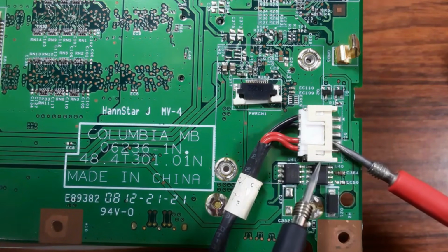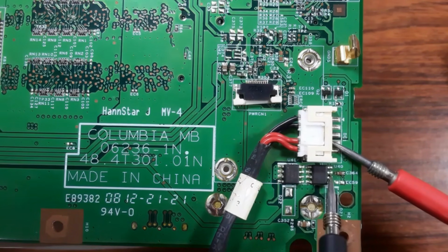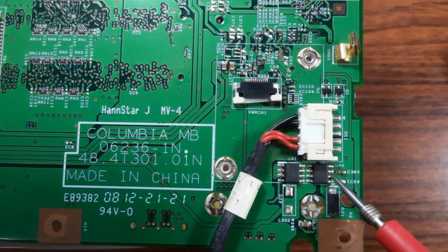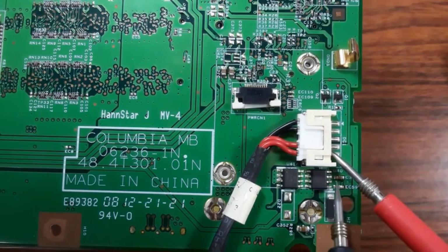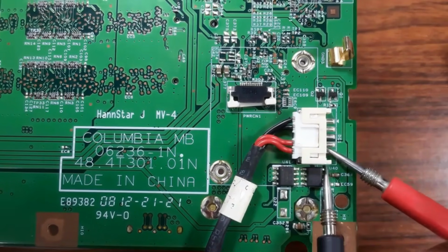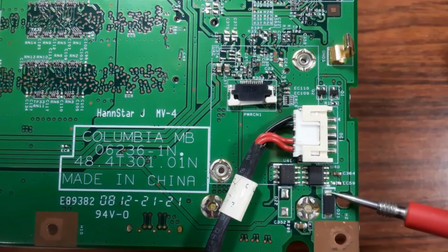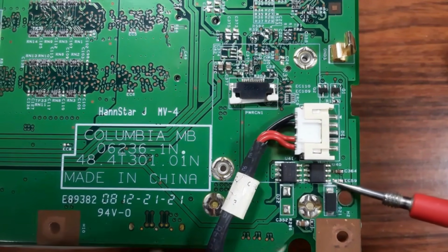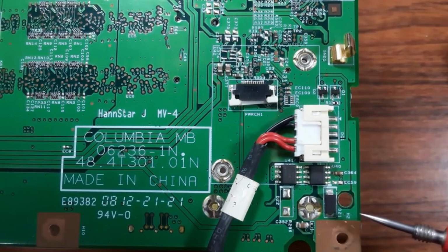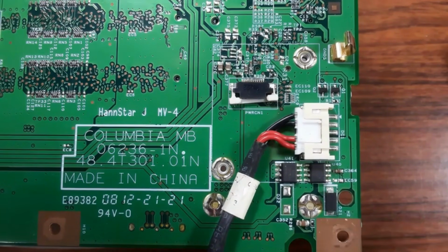So let's track this wire. We have here 19 volts. This path goes directly to here. Why? Because we have the path, as you see. We follow this path. So 19 volt goes to this capacitor, to this Mosfet. Also, we have this diode, D21, also connected to this Mosfet because we have the same path. Then this diode here is connected to the ground.